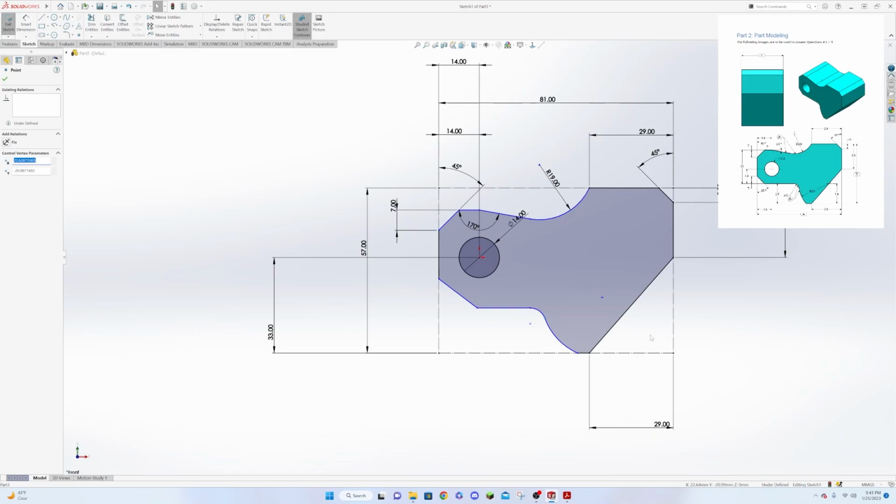Okay. So the next thing we can see is that this center point is coincident with this line. So we can push escape, we'll go here, we'll click on this point, push control, click on this line, and we want to say coincident. So that's going to scooch us over, but it's fine. And then we can look at a few things here. Let's go back over to this edge and start defining from this side over. That will help with some of this.